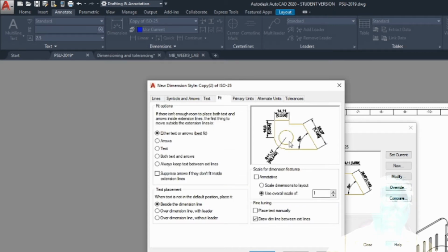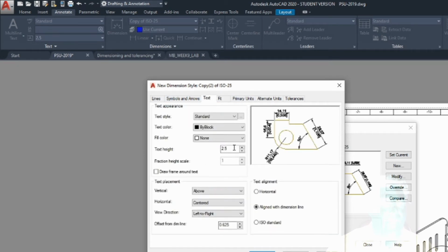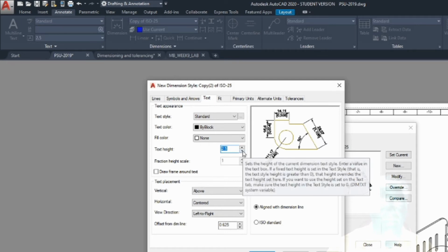And so if you are doing a proper layout, being my CAD is in model space and my drawing is in paper space, then you shouldn't have to play around too much with this. It actually will give you, in this case, the height of the text being 2.5 millimeters, because this is an imperial drawing, is spot on.